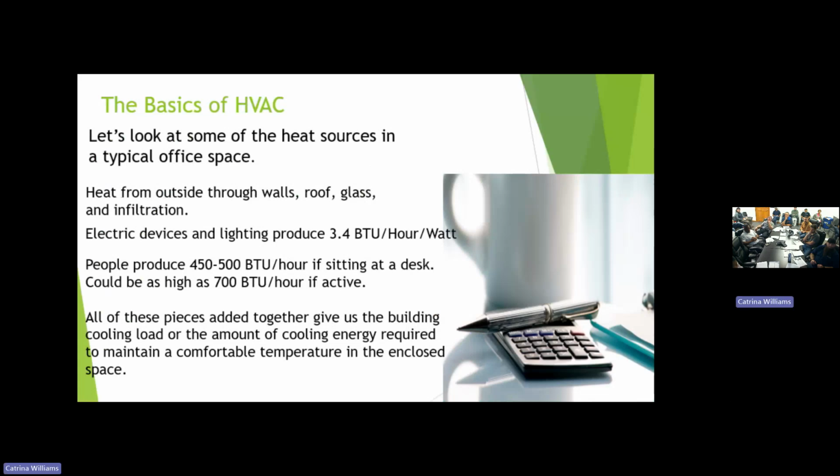But you never thought about that, did you? How many people do we have in the room? 24 people, or at least 20, maybe a little bit more. 24 times 500 is a ton of cooling we need just for the people sitting in here. That's no other load at all, just that load itself. Then you take into account the electrical devices and the infiltration.